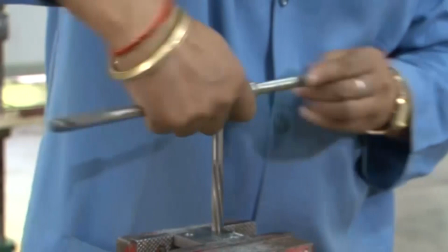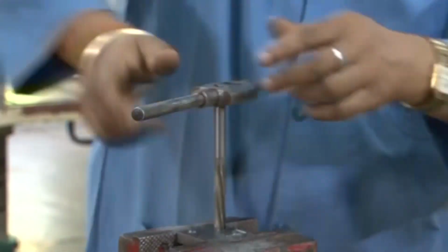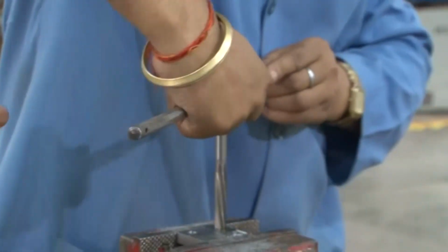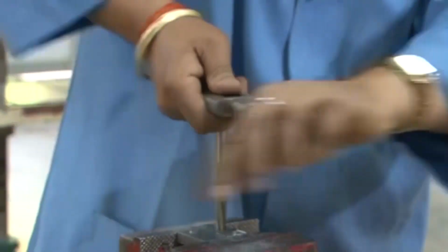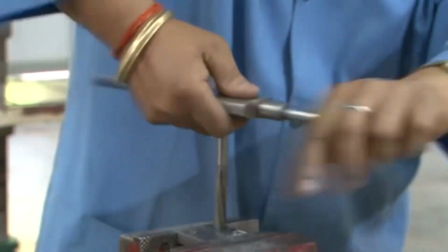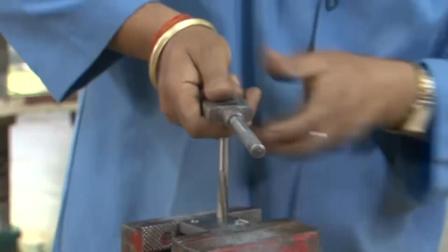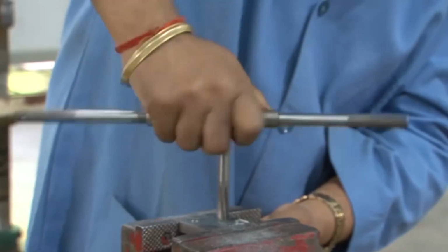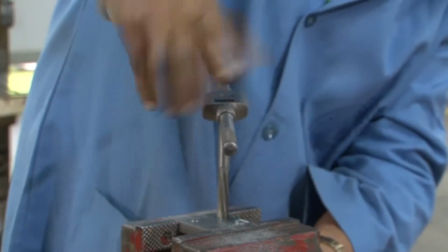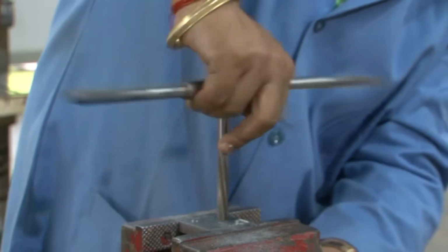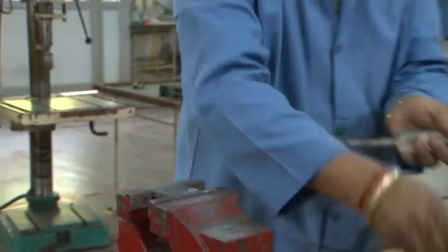If you see the difference between this fluid and the fluid that we used in the machine, you should understand that here it is oil based. You can see there is a bit of oil provided, because here the friction is more important. So, the coefficient of friction has to be decreased, and for that the oil based fluid has been used, whereas in the case of the drilling machine or the turning machine, it was water based. There, of course both matter, but to a larger extent it is the heat that has to be removed. So, now this is reamed.